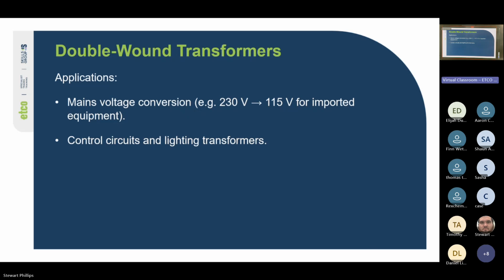It normally came with a little pink transformer, and you had small leads to a little kind of ceramic holder, and you'd plug it in, and it had two metal pins on the back. The dichroic lights are actually AC. They run on 24 volts AC. So instead of having a 230 to 12 volt DC conversion, we just have a straight 230 to 24 volt. So it's just a standard.